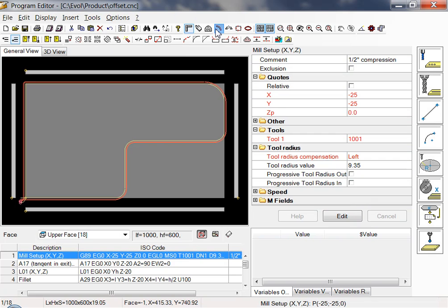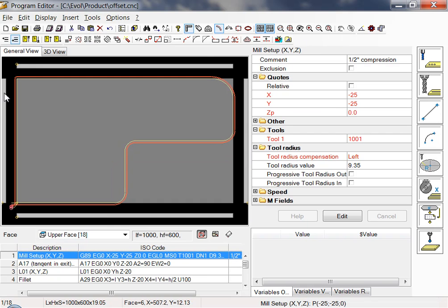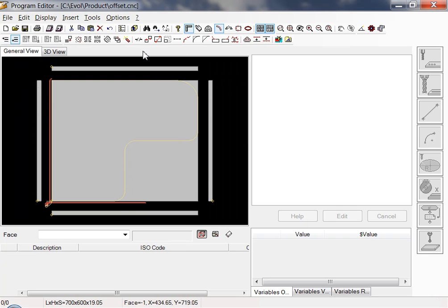And when we do that, now if we look at our offset values as shown by the tool compensation command, you see the two toolpaths are offset 3 millimeters from each other. And with tool compensation, of course, both will roll around the corner. But this way lets us offset the tool from the original value, and it also maintains the parametrics. So if we go back and change the length of the part to something shorter, then of course everything changes parametrically. So use either of these two methods for changing your offsets and creating a quick toolpath when you need to do this.